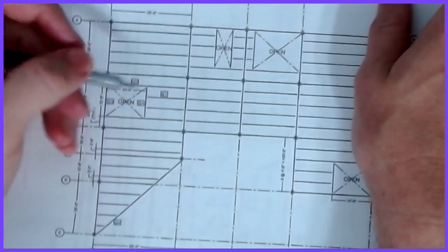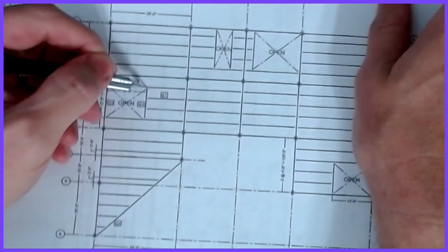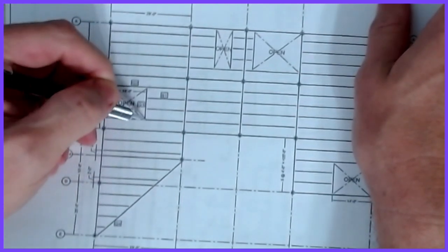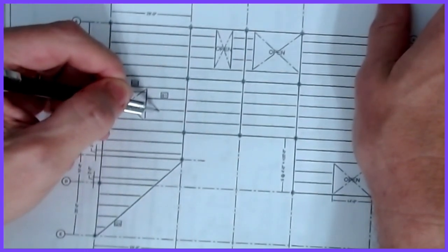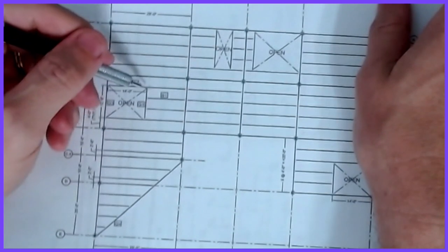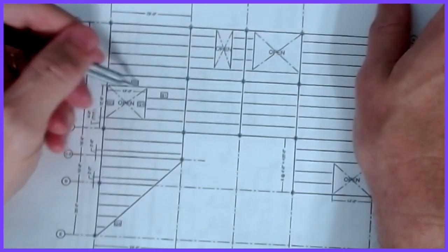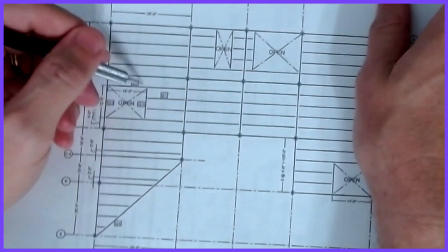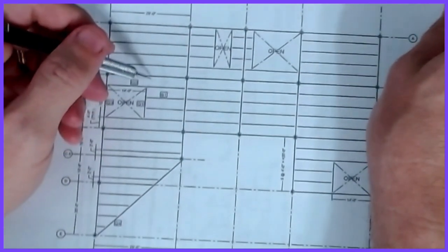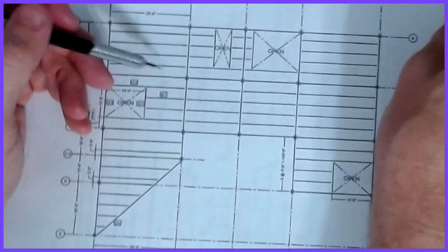But you can still figure out what this G1 looks like. If I assume it's simply supported here, and I assume it's simply supported here, then I would have two point loads coming in from these B1 beams, right? And then this one would put a point load onto G2 at this location, and then this G2 gets half of the tributary width as a distributed load plus a point load on that. And like I say, we'll talk about that next time in the next class. So openings can muddle the process a little bit.